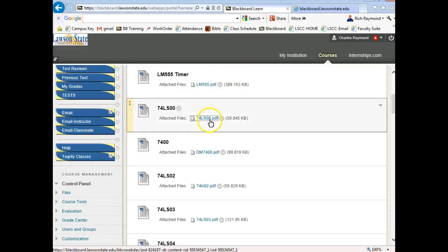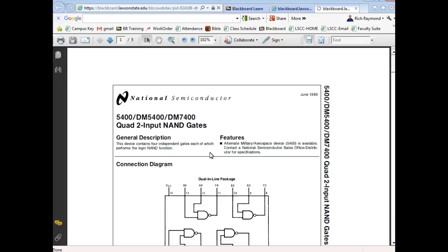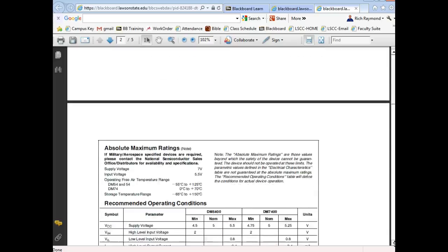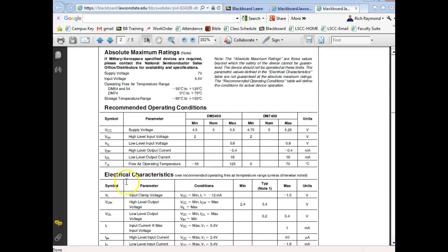So this is the LS. This is the 7400. And of course, when we go out here and look at those same settings, so this guy here for a low, we can drive 400 microamps, which is the same, right? You understand? But all of a sudden, this guy right here can drive 16 milliamps. So this guy could sure enough drive a lot of LSs, right? You understand that? But it can only drive 10 standard series.